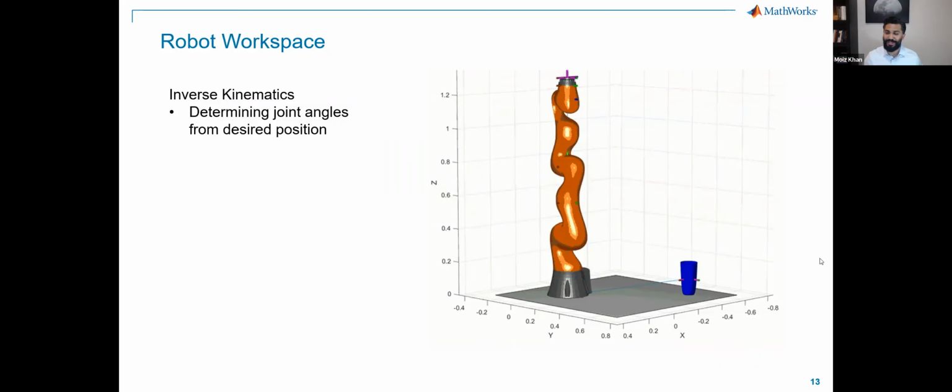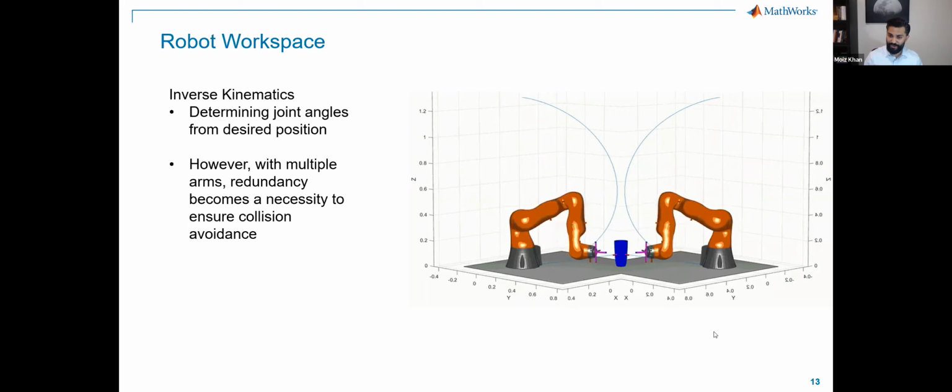What do you do when you have multiple robots, right? So here you're only seeing 2, but in a surgical setting, you have anywhere between 4 to 6 robots. And it could even be more as there's new advancements in the robotics field. Now, it's not about following the trajectory alone. You also have to think about the collisions that can occur. So what you see over here, if you follow this particular path, they collide right over here. And these are type of things that you have to use your computations to account for in your surgical planning. And now imagine having, as I mentioned, 4 or 6 arms. This becomes a very complex task.